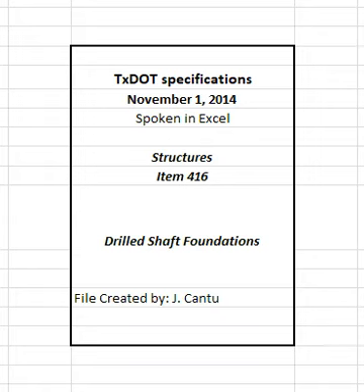3.8 Test load. Load test shafts, if required, in accordance with Item 405, Foundation load test. 3.9 Trial shaft. When required on the plans, construct trial shafts to the depth and diameter specified on the plans. Trial shafts include drilling the hole, placement of the rebar cage, unless otherwise stated, and placement of the concrete.